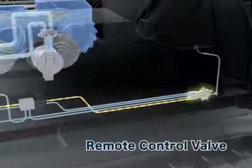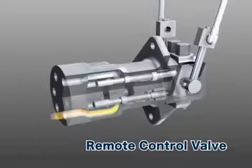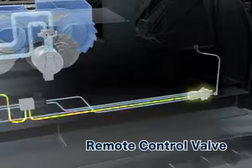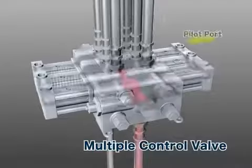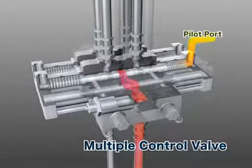The remote control valve is connected to the levers in the operating room, where the operator selects which outlet port to send the oil. Hydraulic oil from the remote control valve's outlet port is sent to a connecting pilot port of the multiple control valve, which then moves the spool.